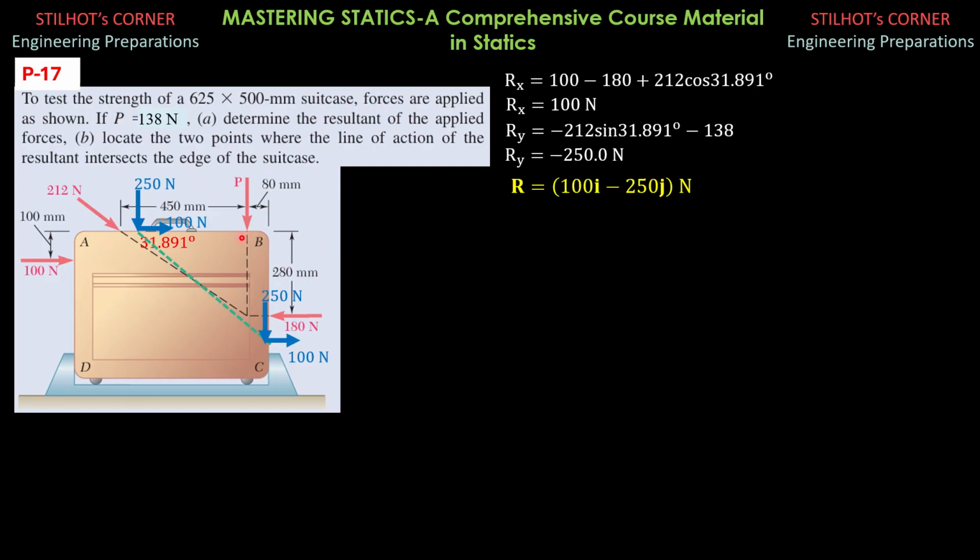Then the moment about B, obviously, if this is the line of action of the resultant down to the right, is counterclockwise about B. So of course, moment summation about B should also be counterclockwise positive. So I use the components first, then to solve for the distances A and B as shown, then I'll use the resultant to find A and B. So moment about B is counterclockwise positive because it is obviously counterclockwise.